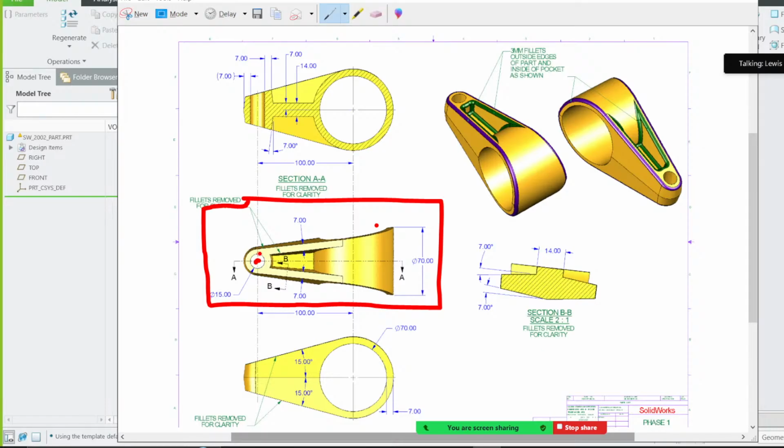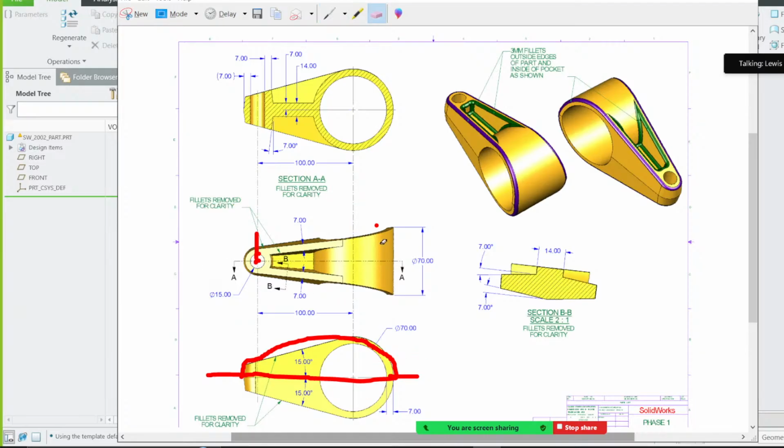We have these two center lines here, and there's this one here, center line. Therefore, it means we model one side, then we mirror to get to the other side. From this view, you can see if you model this half and mirror, you get the bottom side. Therefore, let's start to capture these initial dimensions.